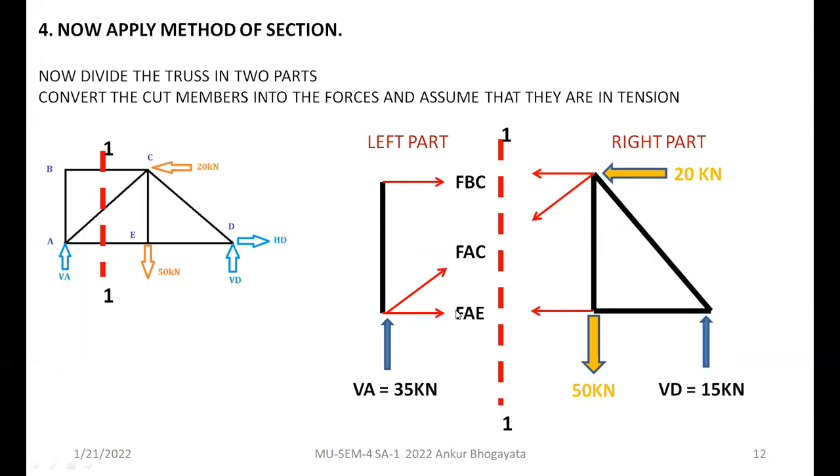And these are the forces because these 3 members were cut here, right? So I have shown them as a force. Am I clear? And also you should not forget the external forces, whether it is a reaction or an applied force. So everything remains as it is. The only thing is when you cut a section, your members become the forces.